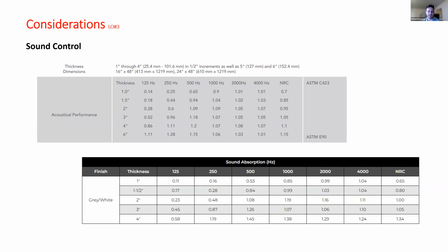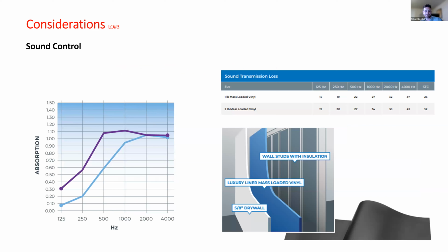I think we've all been in the cheap apartments that we lived in in college, and you could hear your neighbors. All they had to do is add a little bit of extra mass in between the wall systems. When it comes to sound attenuation, the choice of material is pivotal. Different materials like melamine composites and wool offer unique sound reduction characteristics. Certain materials can absorb specific sound frequencies, which is why concert halls and cinemas use specialized acoustic panels to enhance sound quality. A key takeaway is oftentimes you'll design for specific frequencies instead of overall noise reduction.